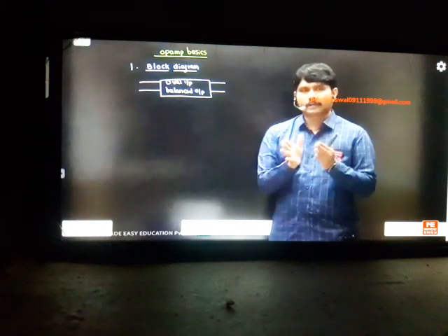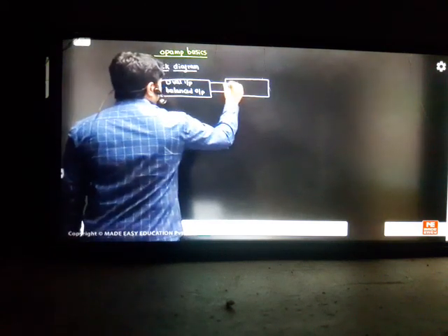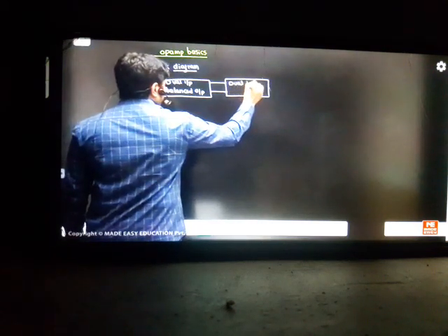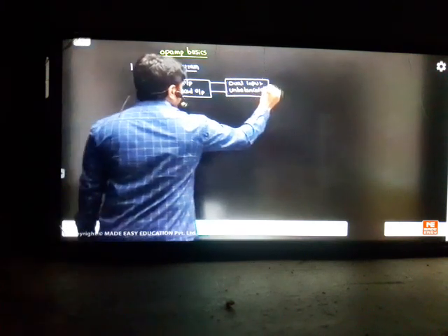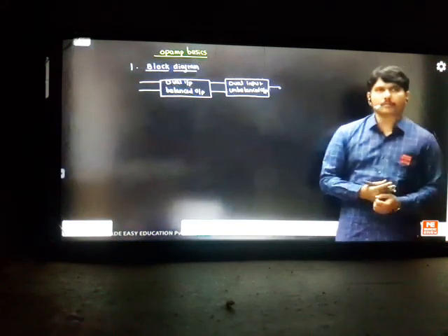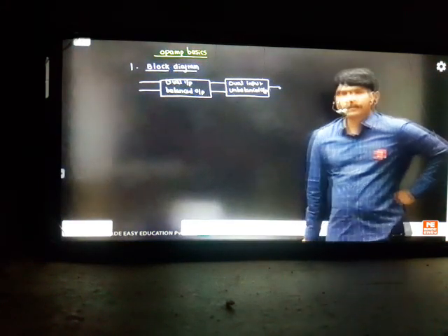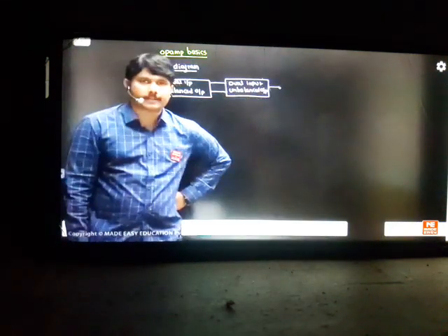So in our design, some intermediate stage amplifier is required. You can take one more amplifier here, one more amplifier to get more gain, called multi-stage. So this is again dual input, but we'll take it as unbalanced output. Suppose I stop with 2 stages, unbalanced output is enough. So I'm taking a 2-stage amplifier; maximum 3 stages you can take, 2 or 3 max. The first stage is dual input, balanced output. The second differential amplifier takes 2 inputs, but I have taken only 1 output from it, because here I stopped my amplifier design. So dual input, balanced output; dual input, unbalanced output.